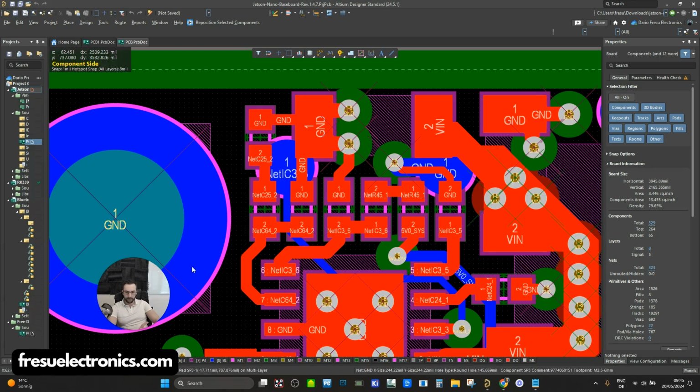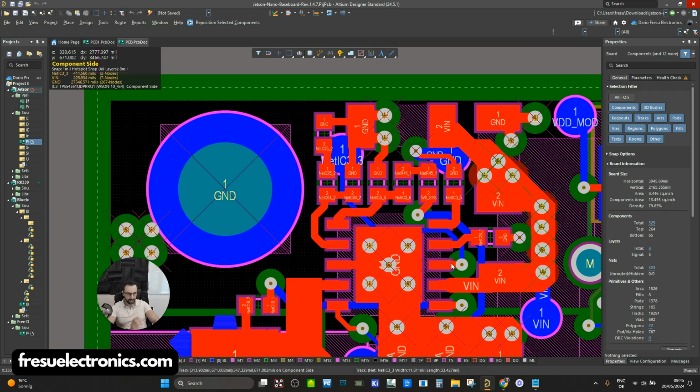So we know that digital circuits are composed of logic gates. These logic gates must switch at a fast rate to provide the required digital signals. For these fast switching events to occur, a transient current in the power delivery network is required. So each time we have this fast switching of the logic gate, the IC will require some transient current, which is going to basically power this switching of the logic gates.